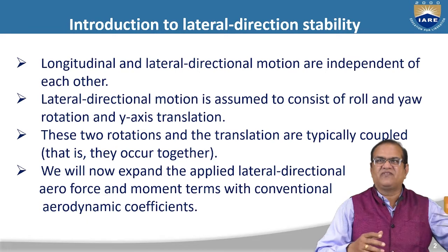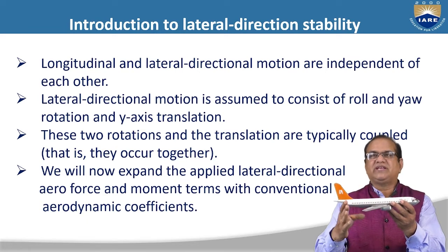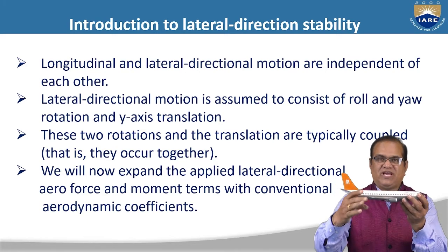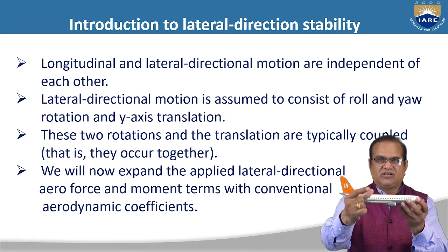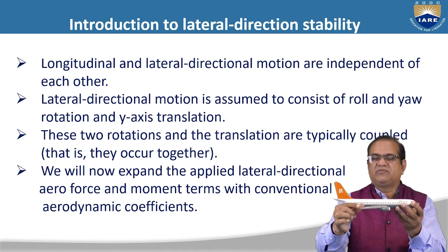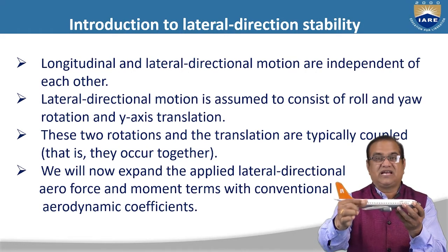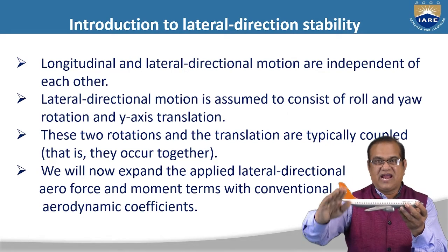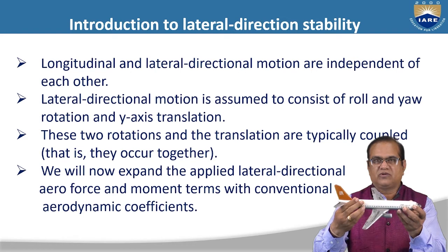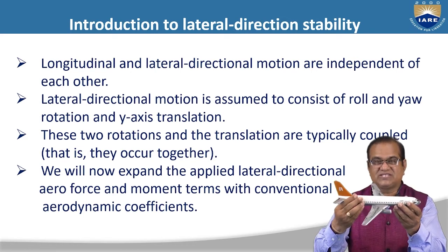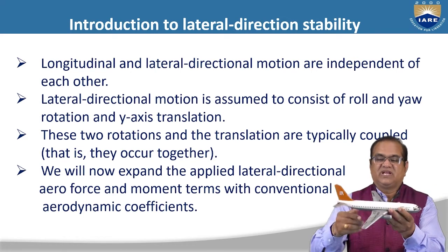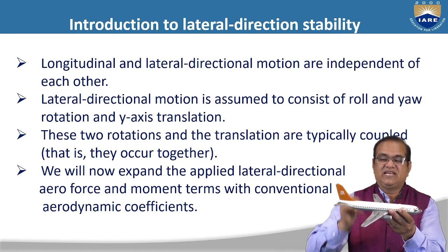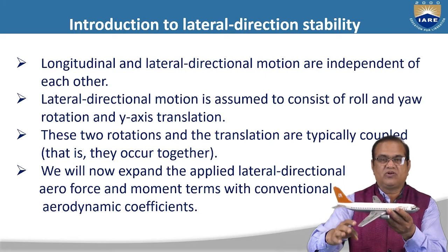Okay, so what is the meaning? I have to explain here. What is the roll? When the wing ailerons are applied, if you apply the aileron upward here and downward here, the right wing will go down. Once the right wing is going down, this side lift is high, this side lift is less.